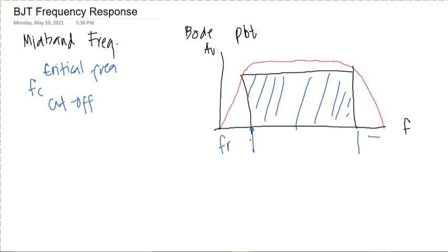In our Bode plot, the unit is dB, or the gain. We move down negative 3 dB, we go down 3 dB from the very top. So we will create a line. We draw the negative 3 dB line from the top, and where it meets our graph, you project it downward, and that will be your critical or cutoff frequency.